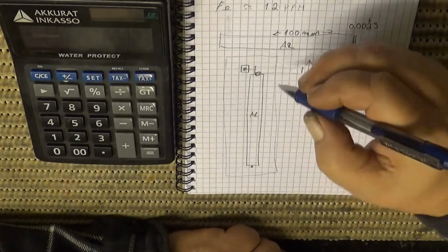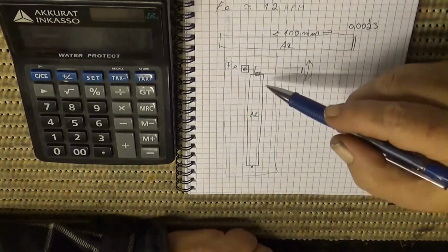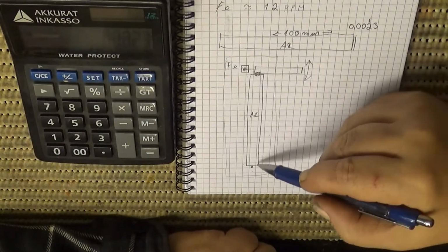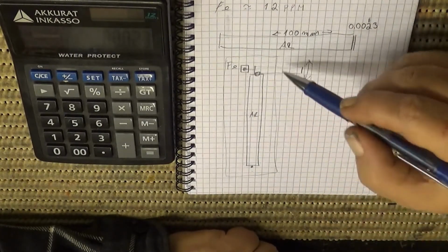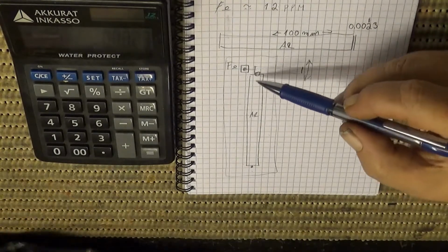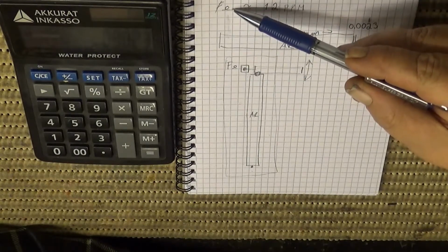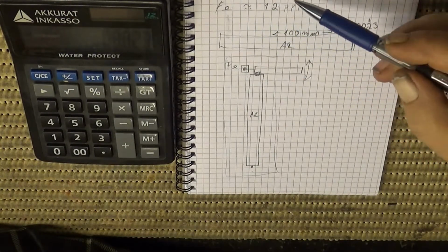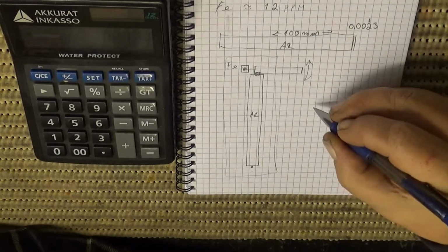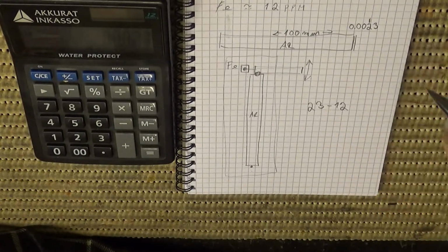But if we make this out of steel, so there is an aluminium part and then a steel backplate, then we are going to have a difference here, but it's not 23, it's actually 23 minus 12 ppm.